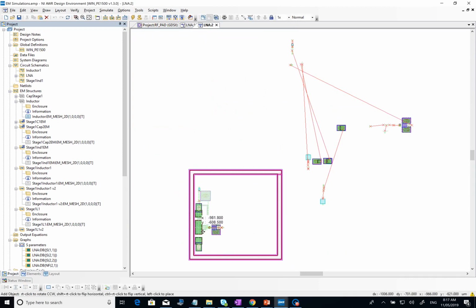So you'll notice that it has to go here, right? If I put it here now and then try to select the other elements, it's very hard, so I'll keep it here, then move this aside. Your transistors, there's a rule that gate always has to run horizontally. Now I could do something like that, but I'm going to run into, see, my inductor is going to run into the ground pad, so I have to tune my inductor again, maybe change it differently.